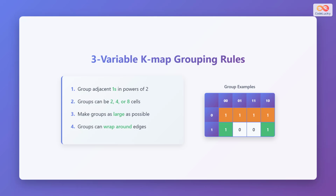Here are the grouping rules for a three-variable K-map. First, group adjacent ones in powers of 2. This means you can group 2, 4, or 8 cells together but not 3 or 5. Make the groups as large as possible. Larger groups lead to simpler terms. Also, groups can wrap around the edges of the K-map. This is because the edge cells are also adjacent. These rules help you simplify the Boolean expression efficiently.